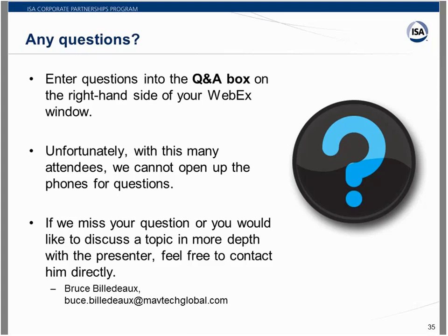Okay, so the next question is, if a vendor wants to connect a laptop to the network to configure, then what care should be taken, as we will not have control over the applications running on his system? Right. So we have various things. The first question to ask, and you can ask this in your PO when you bring a vendor in, is do they already have a program for this? Maverick itself is vendor independent, so we don't really promote any particular vendor. We have some that we are designed to by default, but we're pretty familiar with a lot of the vendors. Many of the large vendors have fairly sophisticated programs for this, so that they have their own engineering laptops, which have a program, and they only get their updates through a VPN to a known site at corporate headquarters for that vendor. They can actually give you that program as part of the PO process.